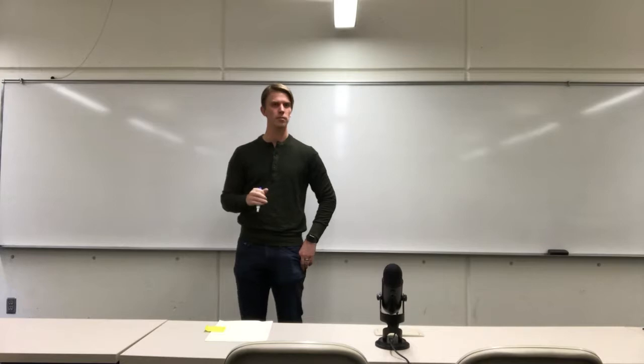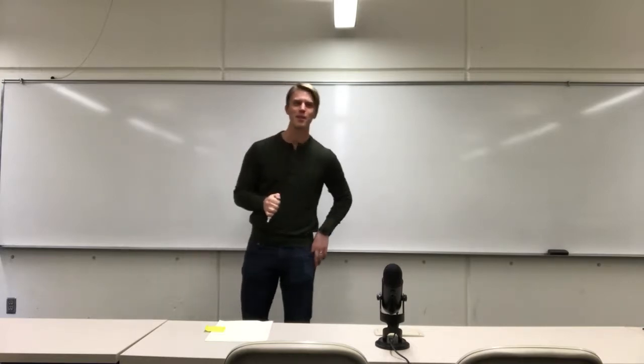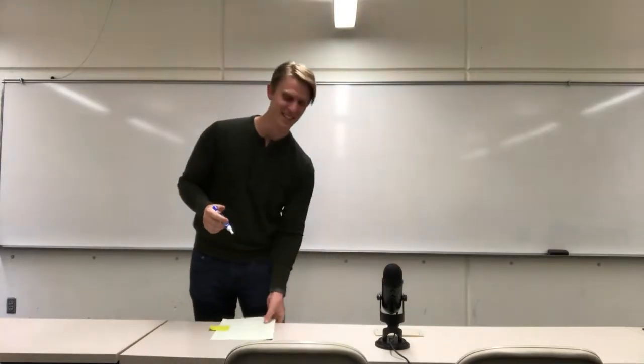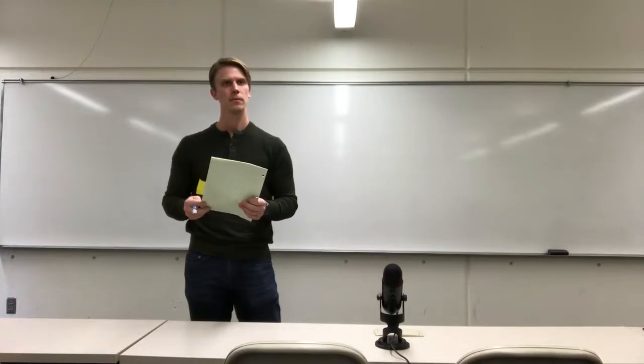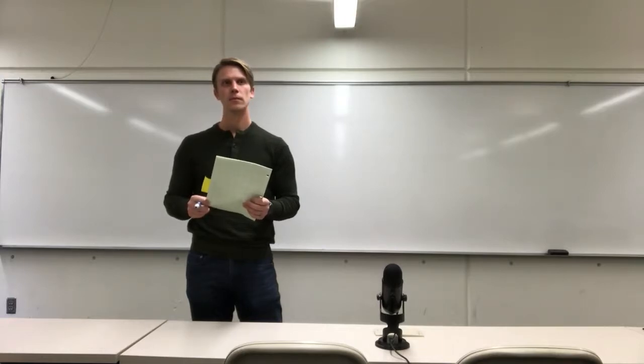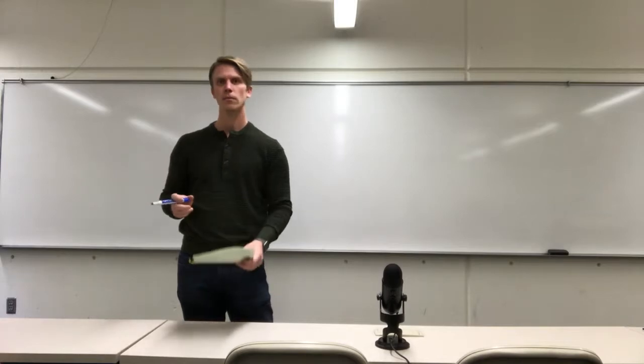Yes, shoot, let's go. So, for number 4B. Which is that one? Sorry, I never remember the numbers. Oh yeah, that's the one where we're making the TXY curve. And so I've got this algorithm that I got out of the book. You pick a trial bubble pressure, bubble temperature, and then you compute Y using Antoine's equation and Raoult's law, right? And then if the sum of all the Y's of all the vapor mole fractions is more than 1, then you reduce the temperature, and the other way around, you increase it if it's too low.